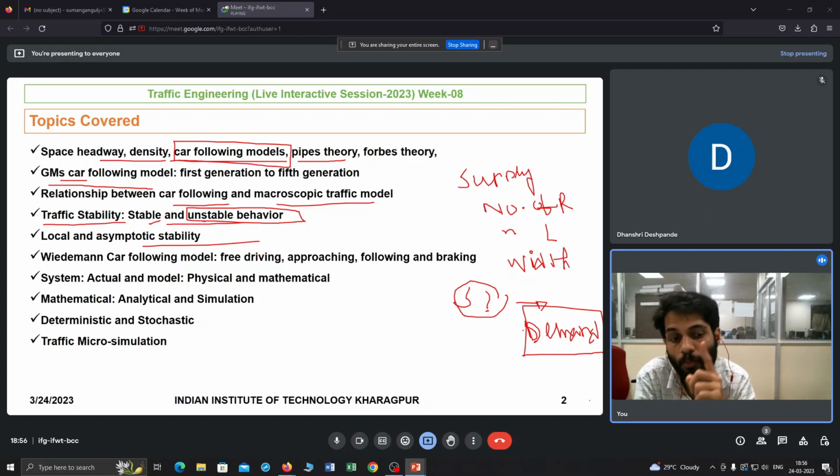Now the car following parameters come. So car following means how your vehicles are interacting, right? So is it following the lanes or not? If it is not following the lanes, what is the behavior? Is the queuing diamond shape, or is queuing normal as we observe in the Western countries or the developed countries? So there are many factors that you have to change or calibrate.